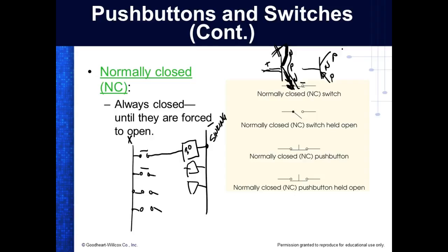That's DC. AC, we don't care. AC has no polarity, you understand. Like I said, Alabama Power is switching polarities 120 times every second. So that means it switches polarities every 8.333 milliseconds, 0.0083333 seconds.